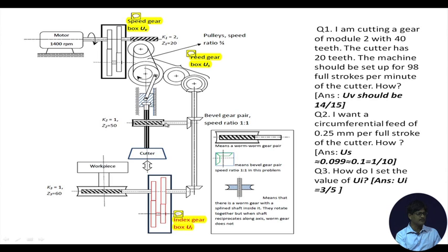And now you are well conversant with this shape. This must be another worm and a worm gear. What's this worm gear doing? Exactly as we previously came across, it's making the splined shaft rotate. But when the cutter shaft is moving up and down, how come this is remaining in position and not moving up and down with it? That's it, because the spline shaft can move through bodies without sharing its straight line motion.